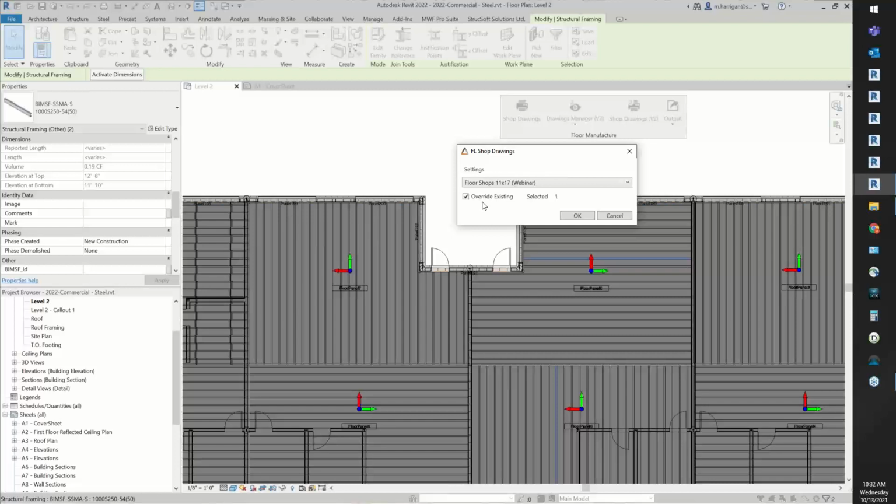You do some modifications. So when it comes to shop drawings, we ask to select the panel that has a lot of detail, get that one the way that you would like it, and then from there select the other ones and create your shop drawings. Because any settings you do physically to the sheet itself, it only affects that sheet.